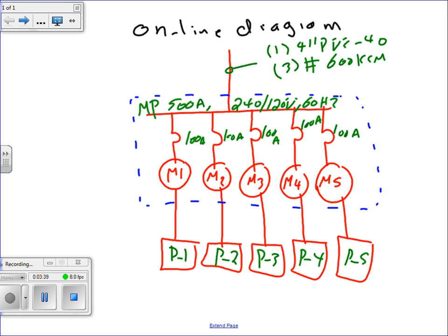Why 1 conduit? Because we're going to put them all in 1 conduit. Why 3 conductors, 2 hots and a neutral? Now, tell my friend what happened to the ground, Chad. Do we bring a ground from the utility to the building? No. We only bring the 3-phase and a neutral, or the 2 hots and a neutral. No ground coming from the utility transformer or power line into your building. You create your own ground.